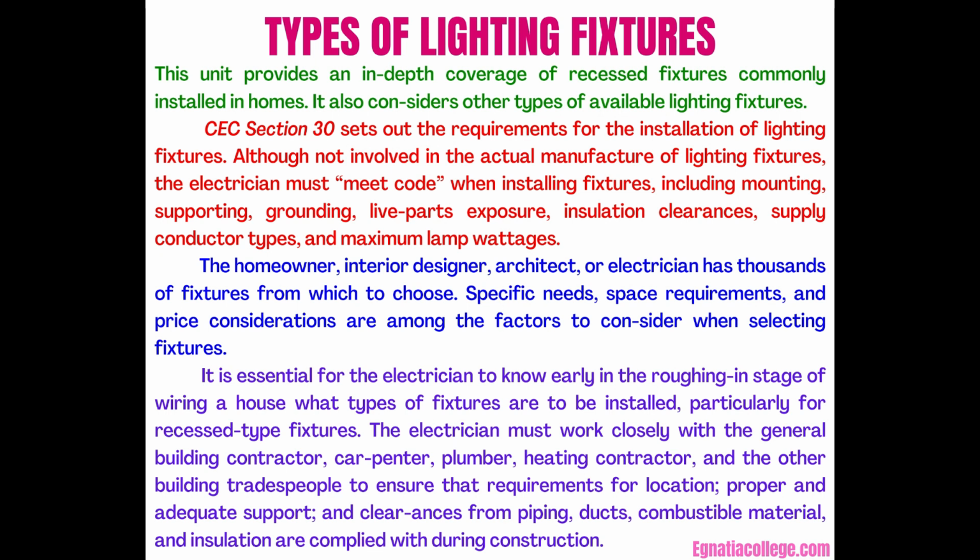Although not involved in the actual manufacture of lighting fixtures, the electrician must meet code when installing fixtures, including mounting, supporting, grounding, live parts exposure, insulation clearances, supply conductor types, and maximum lamp wattages. The homeowner, interior designer, architect, or electrician has thousands of fixtures from which to choose. Specific needs, space requirements, and price considerations are among the factors to consider when selecting fixtures.